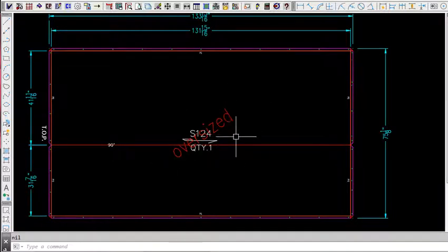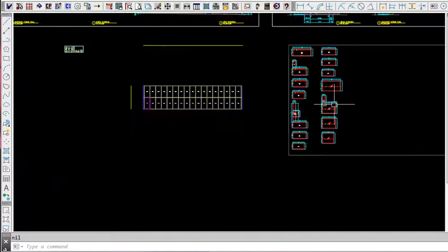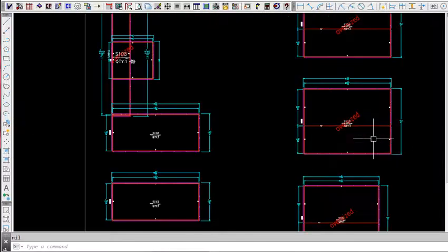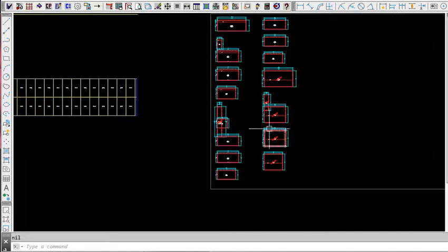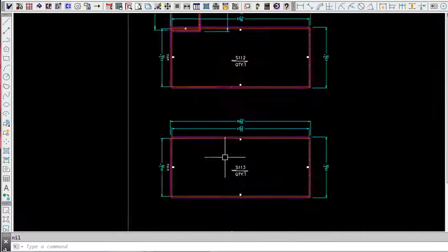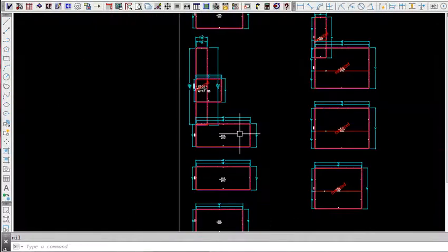So right here, this is one of those outside corner panels, and it says, hey, it would have been okay if the grain was going this way. However, it's still too long to do it that way. So this needs to be revisited because it's not valid. That's why you've got these oversizes right here. And I thought, hey, that's pretty cool. Anyway, that's how the grain works. You just assign it.